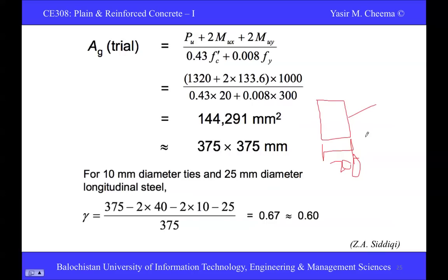So in this example, the writer goes with 375 mm, so let's get an understanding this way. But when you are restricted to a rectangular column, you can take any dimension that should be less than 375 mm as described in the question. The other dimension you can find from the area.